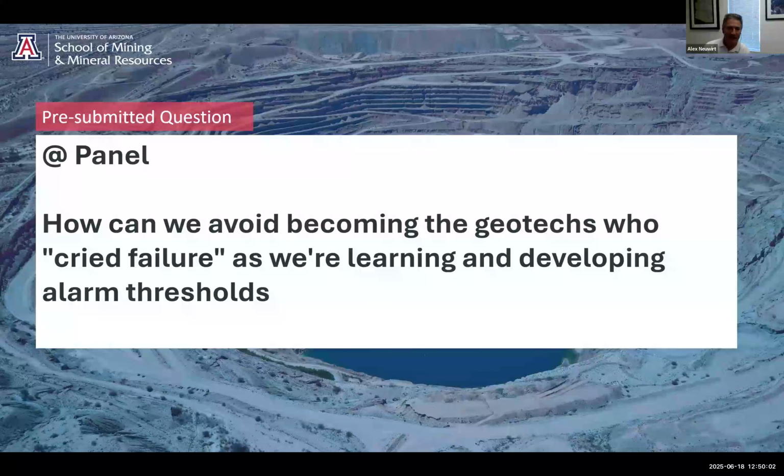So what's the learning and developing process there? Well, somebody should be looking at, hey, why is this flashing every 8 seconds? Maybe we need to adjust the boundaries of the alarm area. Maybe we need to adjust the alarm values. What is actually happening? As opposed to just getting stuck in this, every 8 seconds I have to go look at the screen. There must be a process of learning and developing. Anyway, is that where you're coming from, Paolo?